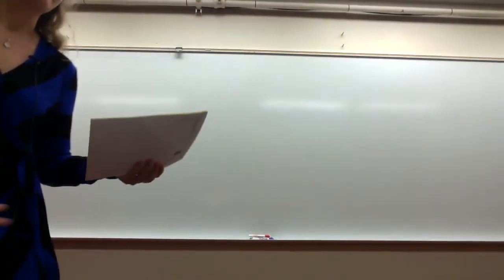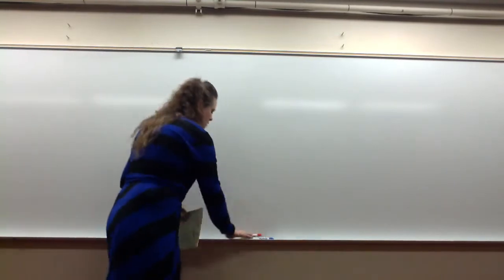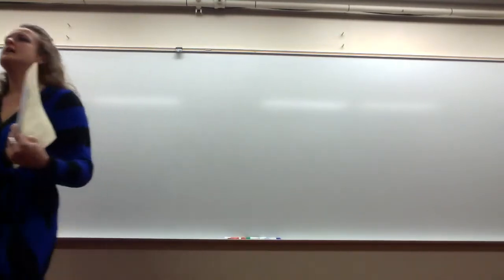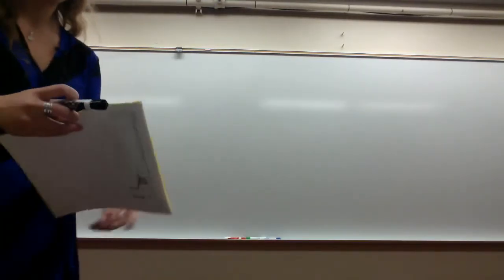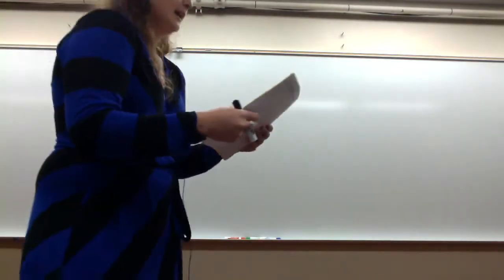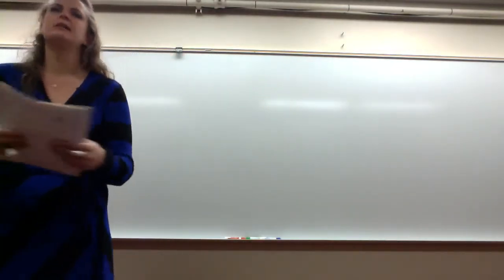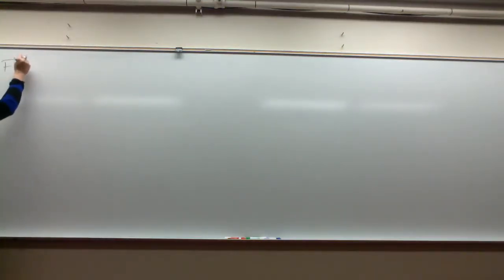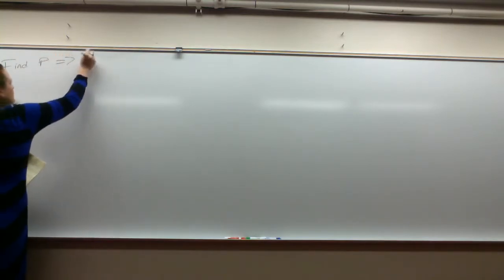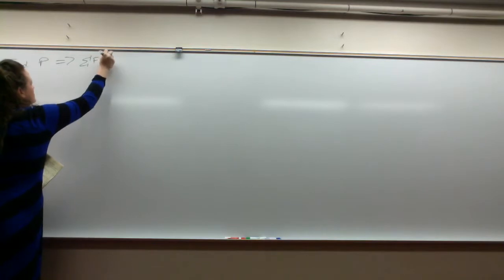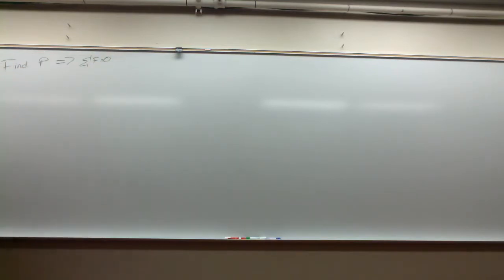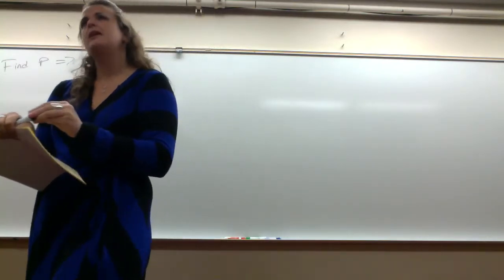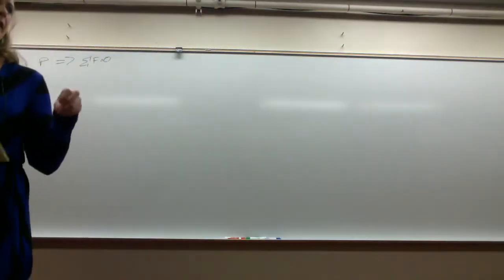So let's derive what that actually looks like in terms of our methods with machines. If we want to find the minimum force P in this system that will maintain equilibrium, that will maintain the sum of the forces equal to 0, just before we even start solving this, is P going to be bigger or smaller than our load?